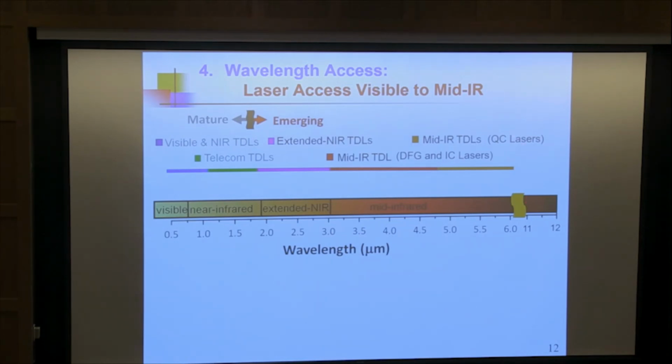somewhere, there it is. So as you change wavelength regions, you change the band gap. The band gap is determined by the properties and the thickness of the layer. So it's all about material science and fabrication. But nowadays you can buy almost any color you want, ranging from, well, there is a problem down here. The shortest you can get with a CW diode laser that's not frequency doubled is probably around 750 nanometers. And there's reasons why I'd like to be a lot shorter.